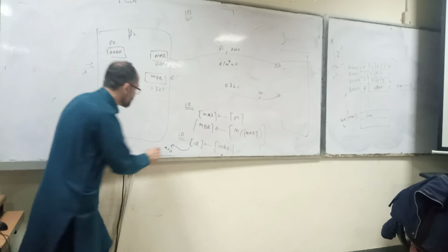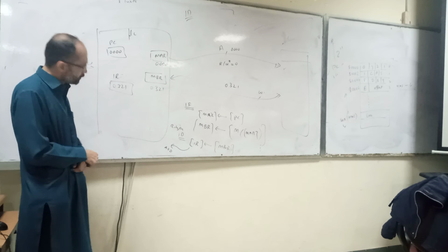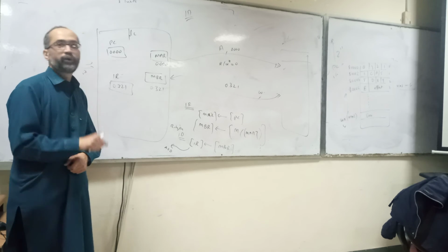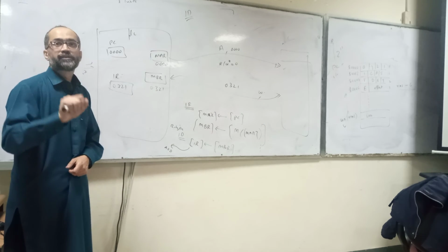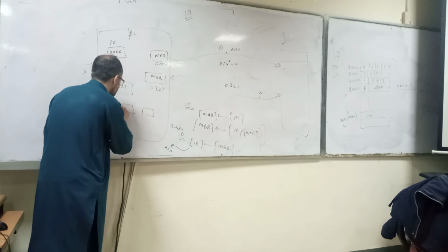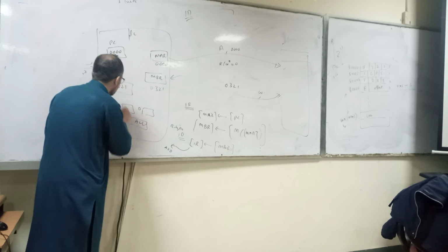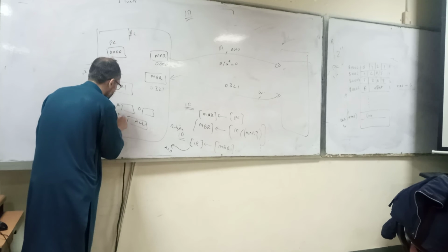What type of instruction is this? R type. Okay, this is an R type, so we need to add. What do we need to add? Two registers. So there is some ALU. We have a temporary register A, a temporary register B, and now you have an ALU. For this ALU, the output field is done. So we say that now we need to add.